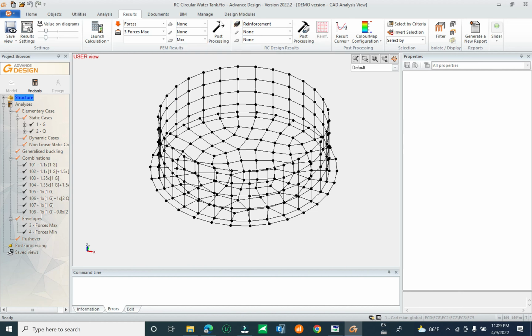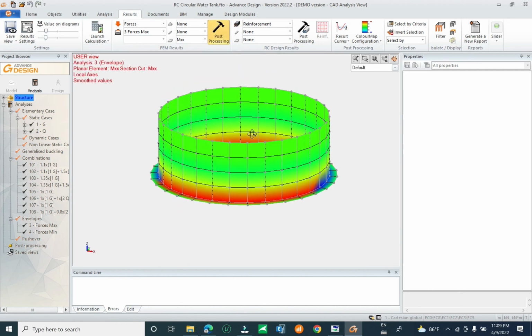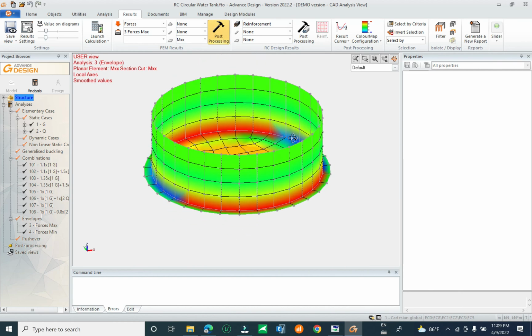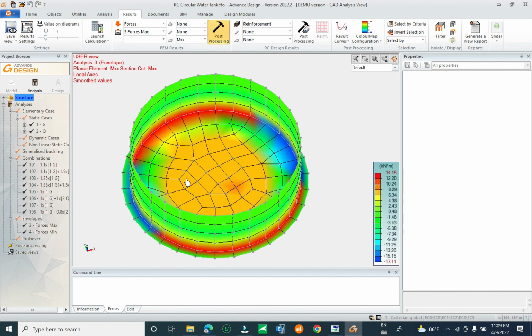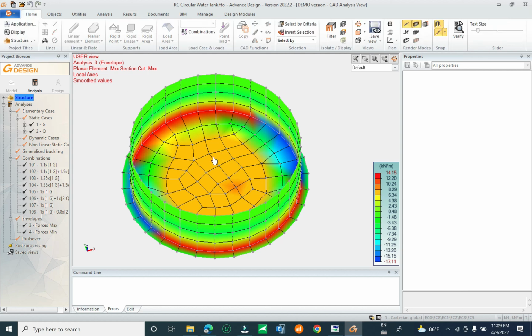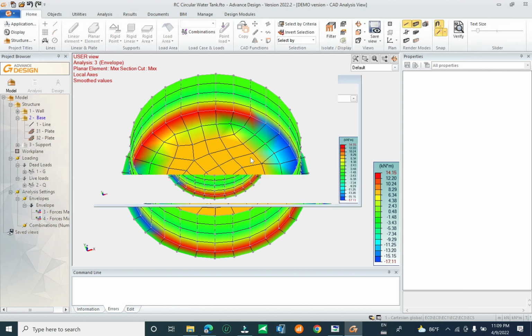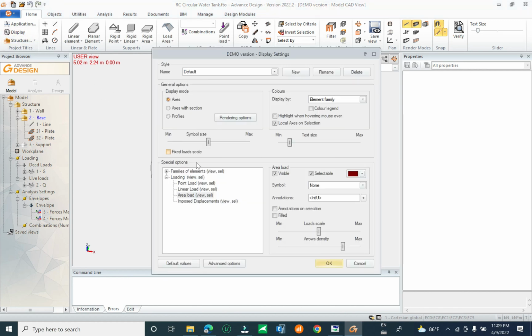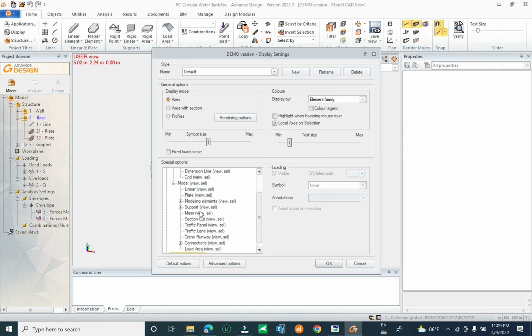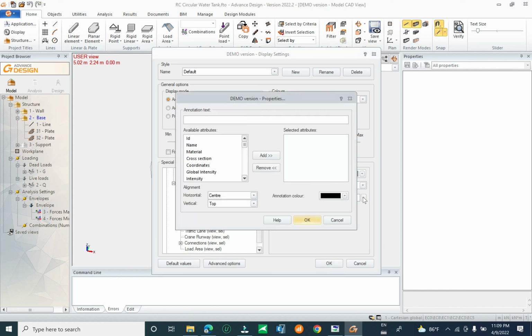In each, you can see here for the maximum moment about in each for the local axis. You can display for local axis to check where is the each direction. You can display, click on the family, geometry, model, is the plate, and show the local axis.